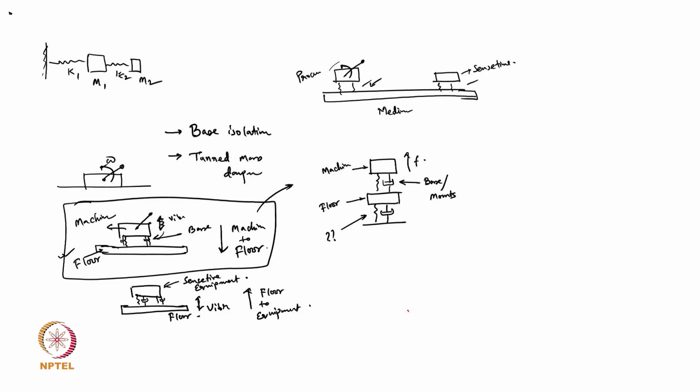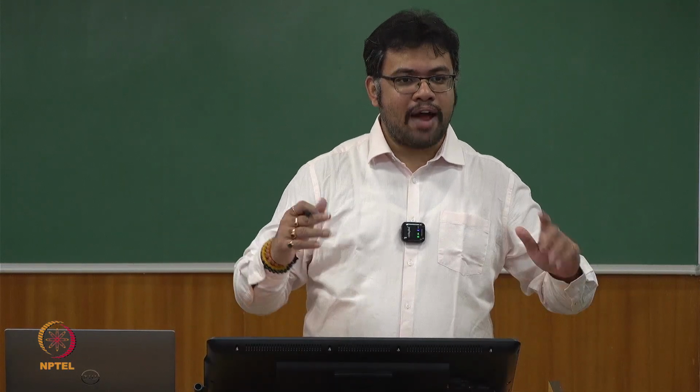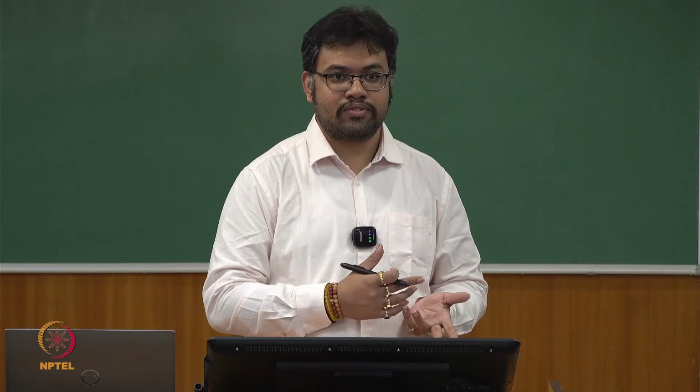Columns and slab. Exactly. But just one point, if you think columns will be in the horizontal direction. If you are thinking that this vibration is creating horizontal motion, then his point is very correct that it will be like a column stiffness. But if it is producing vibration in the vertical direction, then you have to consider the flexibility of the beam and slab. Agreed? So you have to actually start feeling the problem, what you are actually solving. Get that point?